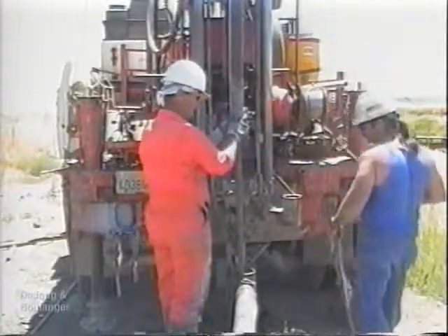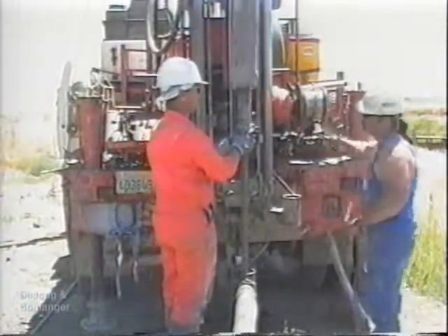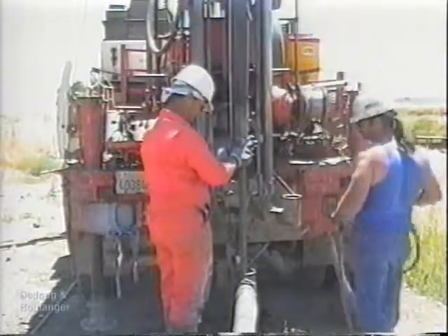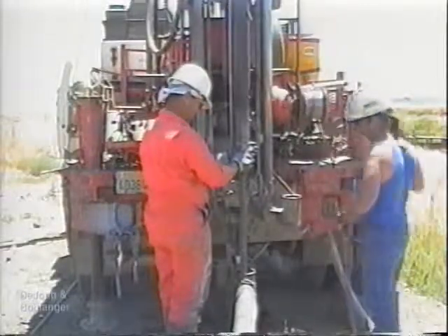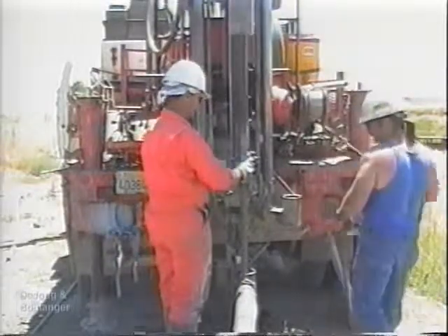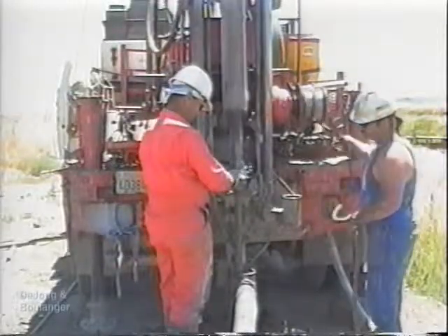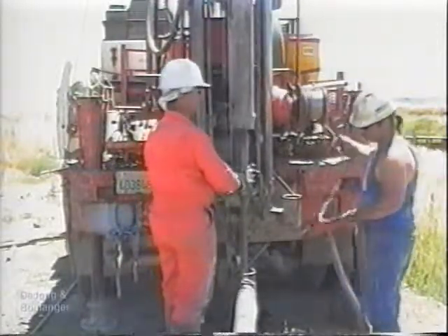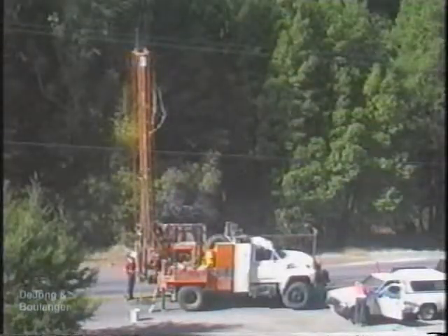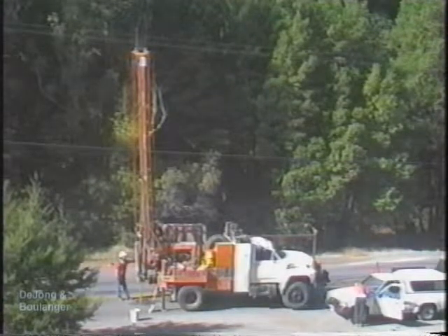Generally, the better the quality of the sample, the more expensive and time-consuming its recovery is likely to be. For some purposes, such as designing the foundation of a light structure on stiff clay, the expense of obtaining high-quality samples may not be justified. On the other hand, when the compressibility or shearing strength of soft clay is needed to evaluate the settlement or stability of a critical embankment or structure, even the best samples may barely be adequate. Consequently, there is a need to establish a quantitative measure of the quality of samples, especially for soft clays and silts. This video has presented a basic introduction to some of the common drilling and sampling procedures used in geotechnical practice.